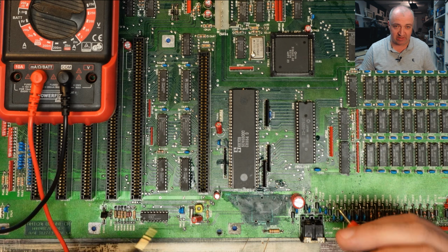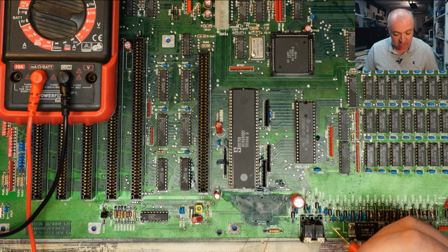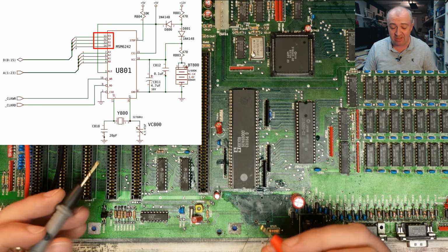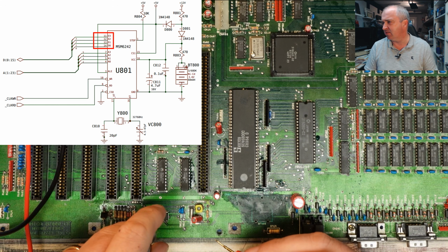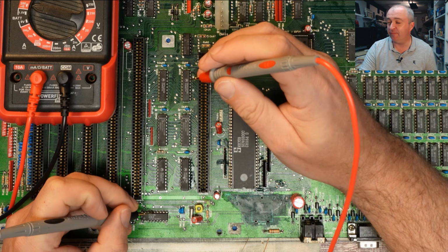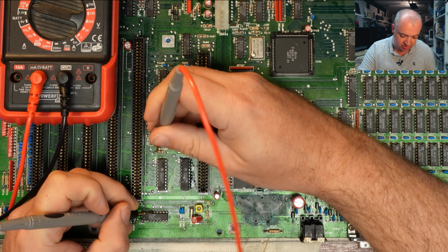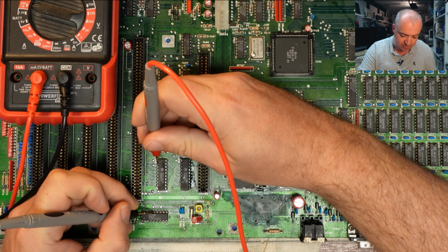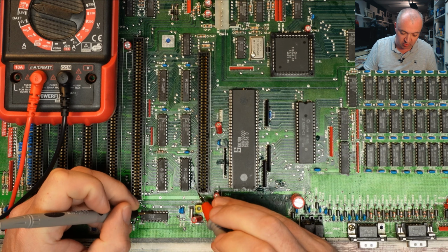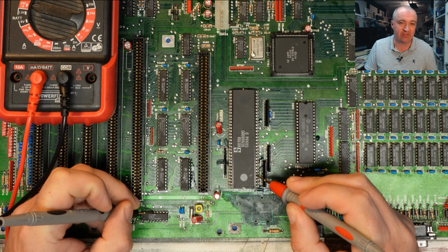But equally, I think it's the issue on the real-time clock, because that real-time clock chip has data lines D0, 1, 2 and 3 presented on pins 11 through 14. D0 is on pin 14 on this, which I think should buzz out onto our buffer here, which it does. But equally, that's going to be broken back to here, back to the CPU. I think that's going to be the problem.